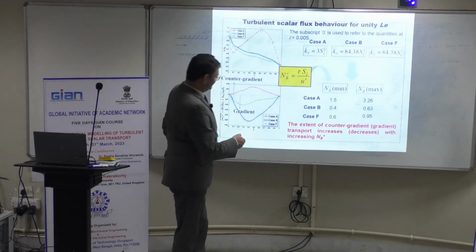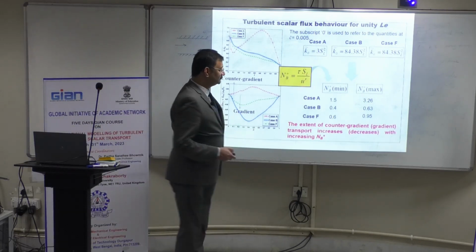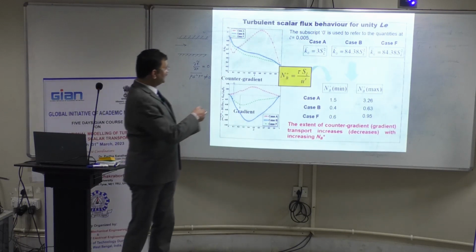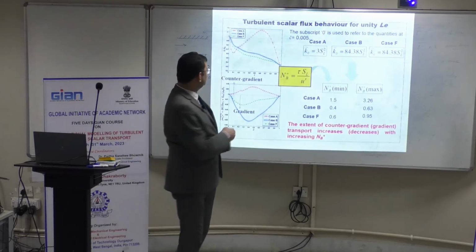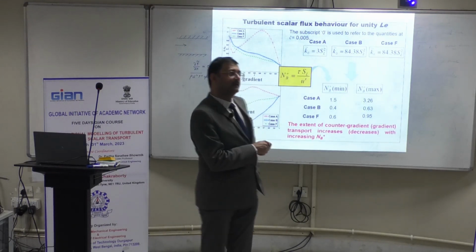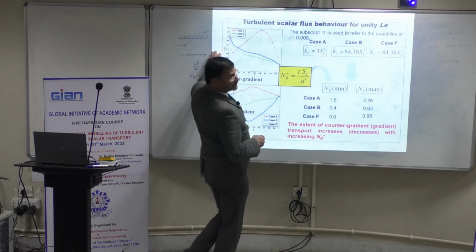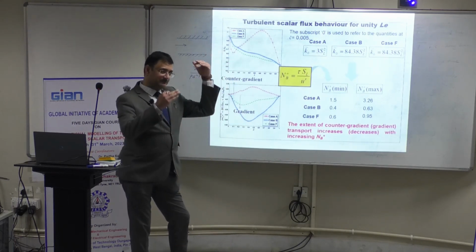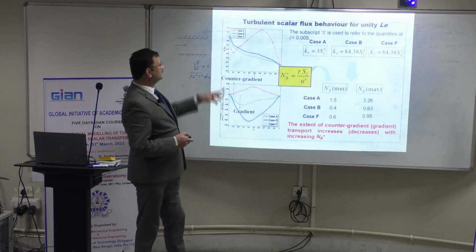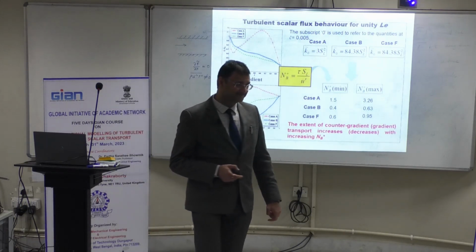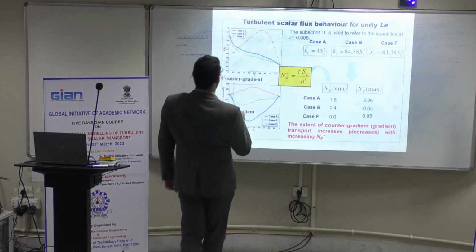If you look at the Bray number, based on the values and the behavior, this is the turbulent kinetic energy behavior as a function of turbulent kinetic energy at the leading edge of the flame, that means towards the unburned gas side. You can see the behavior is completely different. This is Lewis number 0.34.